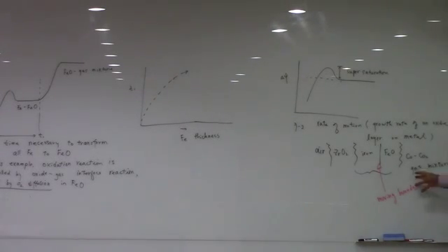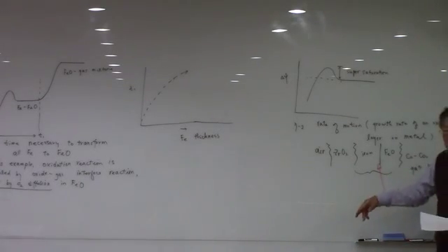The important thing to notice here is that this moving boundary is not controlled by the diffusion of oxygen in the FeO, but controlled by the surface reaction at the iron and FeO interface here. The chemical reaction controls everything, not the diffusion of the electroactive species in the cathode.